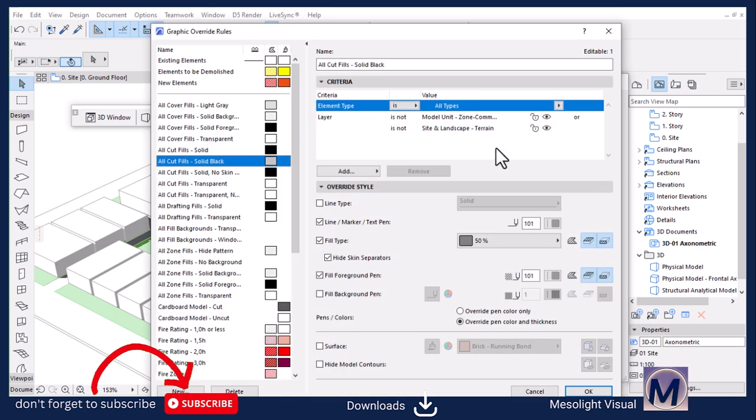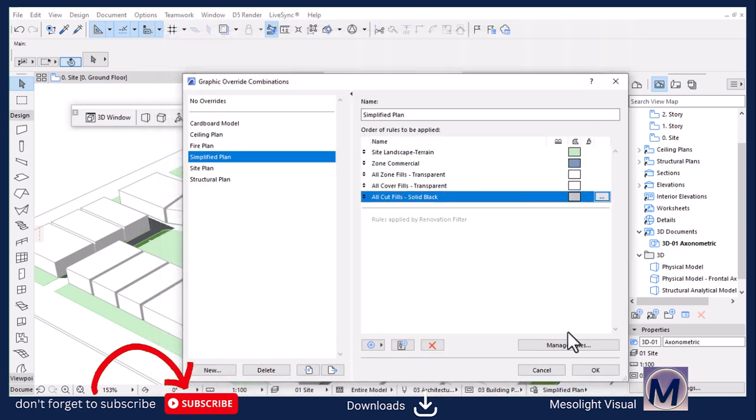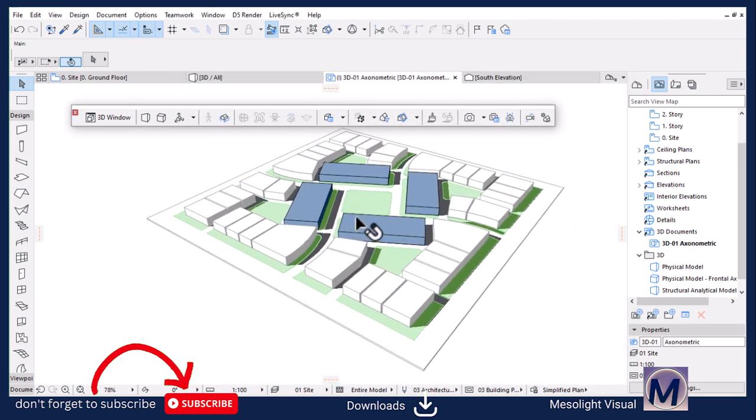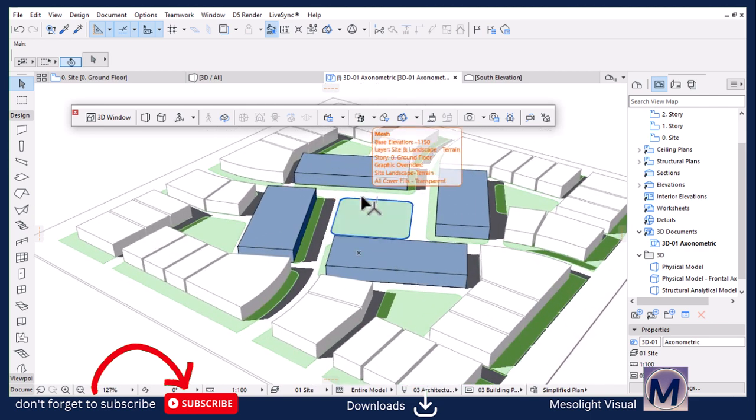So if you say edit rule, we have a layer combination that says the problem here is if we say or, it won't change. You need to change it to and, because to get the ruling, because you are saying it's not, then hit OK. It's kind of how ArchiCAD works, guys. So it's important to understand those. Now we have our commercial plots back to its normal.